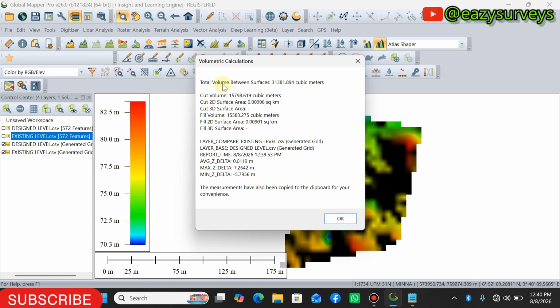Like I said earlier, Global Mapper makes use of the grid method of volume calculation, but Civil 3D makes use of the TIN surface method for volume calculation. Engineers, basically, we do love to go with the TIN surface method because that gives a better form of calculations. Although this grid volume method also has its own advantages in some ways.